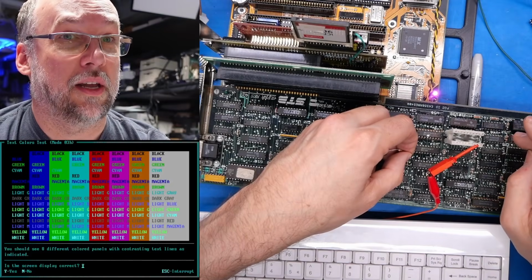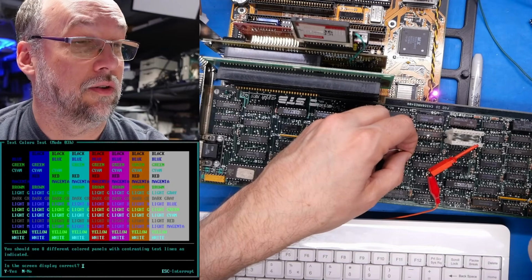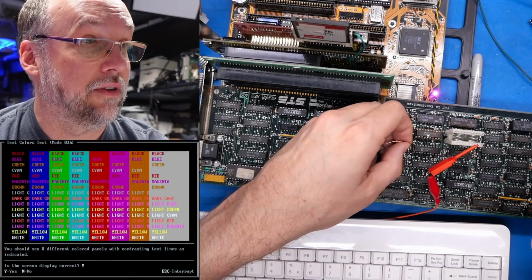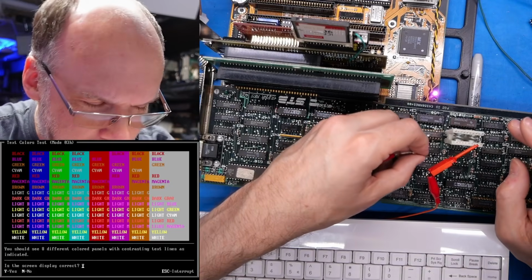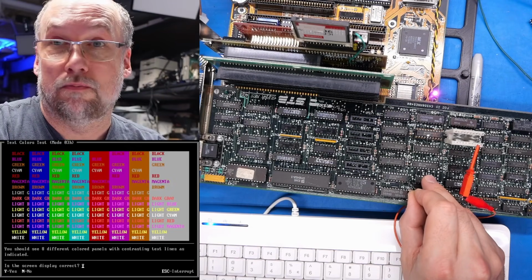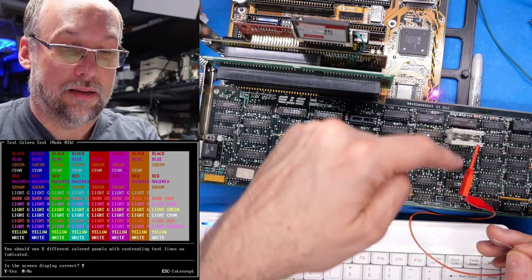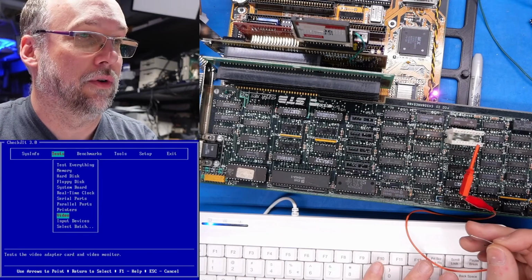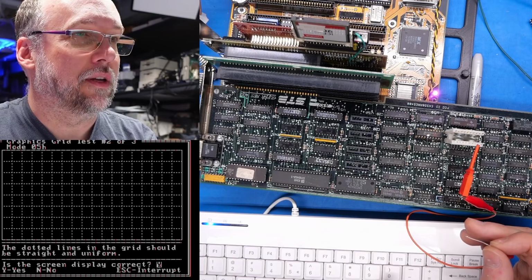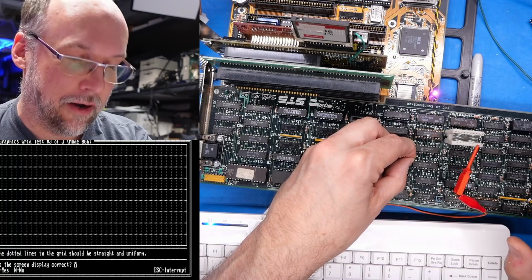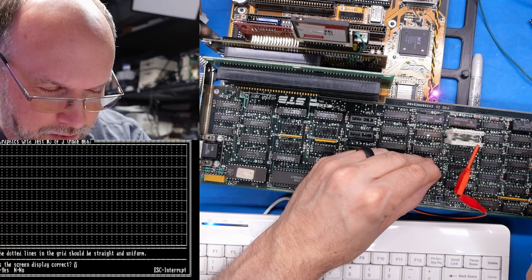Okay, so first I connected to ground, and there it is. So absolutely, that pin is responsible for the attribute color that we're having the problem on. When I pull it off, it goes away, and if I connect this resistor to 5 volts, no change whatsoever, which is kind of what we would expect, because it seems to be just sort of internally pulled up to 5 volts. Now, when we go to the graphics mode, on the other hand, I don't think doing anything with this, ground or otherwise, so that's on ground and there's no effect, or 5 volts.